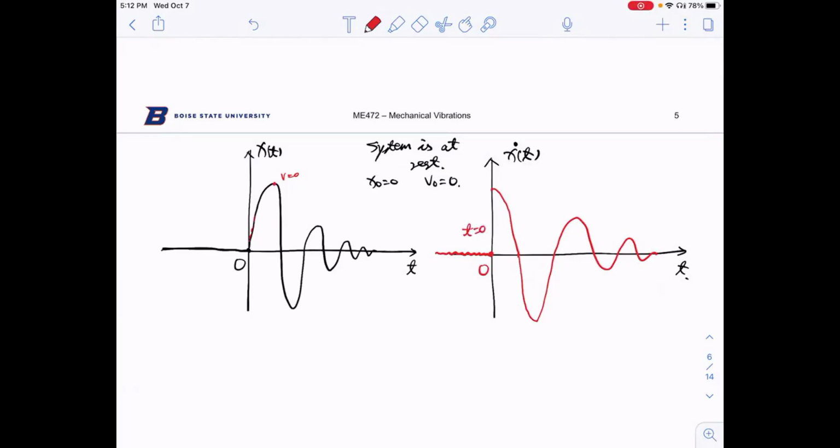But then there is a special location when time equals 0. What happened to the velocity? Well, technically, it's going to be going towards infinity initially, right? Yeah. So mathematically, we call this point the discontinuity, right? Correct. So that's because you have an impulse. In other words, an impulse excitation is going to create a discontinuity in your system.